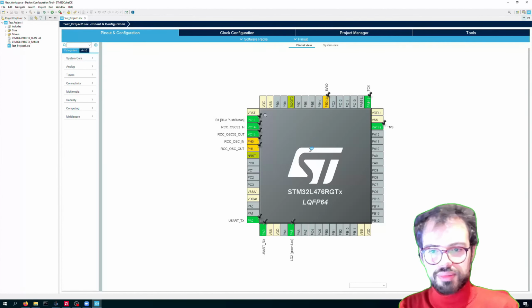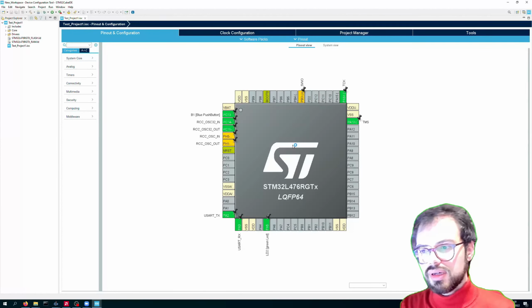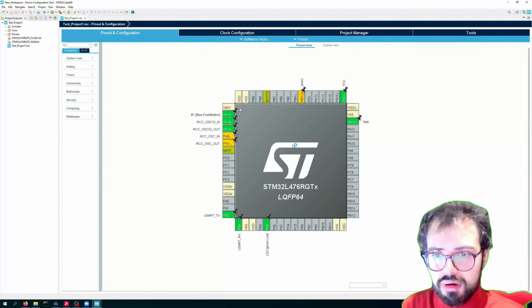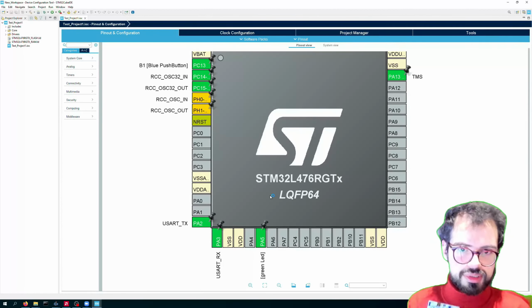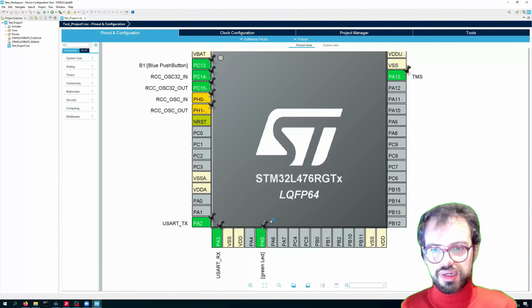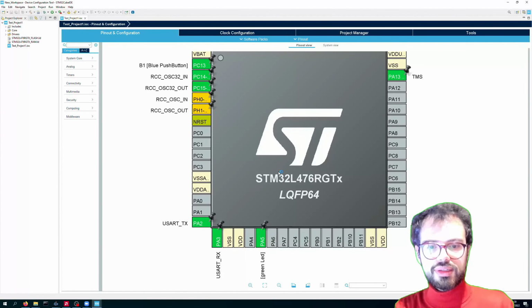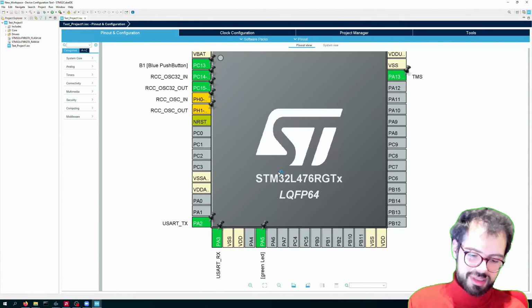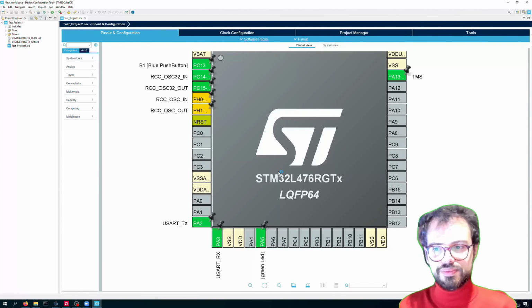So we will start immediately with a very quick hello world project. Let's say that we might want to just turn on and off an LED like this one. You can see that in this board specifically, and that will be pretty much the same on the others, the GPIO PA5 is directly connected to a small green LED that you cannot see here, of course. At the moment, it's not visible. When it will be on, eventually, you will be able to see that.